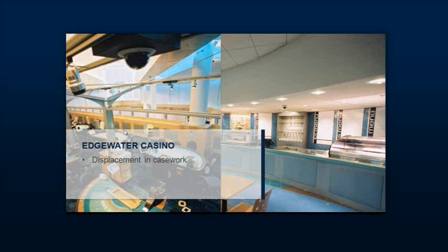Now, what I really love about this building is the end user went to the engineer and sent them a data file, which they then shared with me, that they started monitoring the temperature in this building in October, I believe it was last year or the year before. They started at 6 a.m. and they measured the space set point and temperature sensor in the space. And they went from 0 occupants at 6 a.m. to 125% of occupancy at noon. And the temperature inside this space did not vary by more than 1 degree,